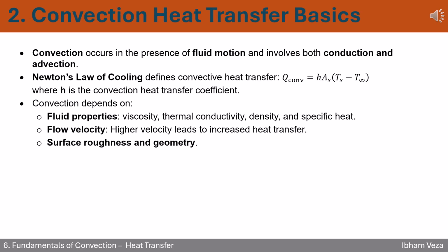2. Build a strong foundation with convection basics. Let's begin with the fundamentals. Convection is more than just heat transfer. It's a combination of conduction through fluid layers and advection due to fluid motion. A key principle is Newton's law of cooling, which shows how heat transfer rate is proportional to temperature difference, governed by the heat transfer coefficient h.